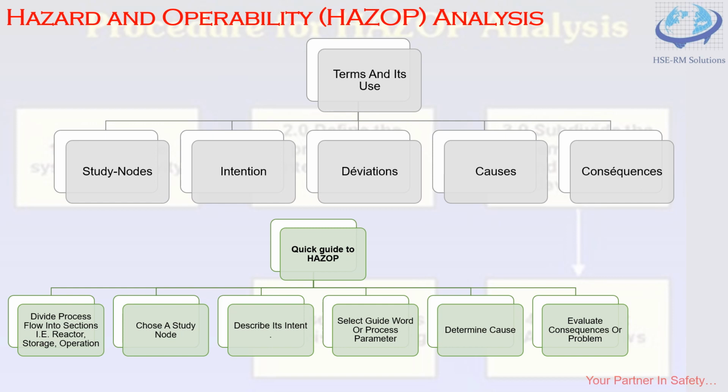These are reasons why a deviation might occur. Once a deviation has been shown to have a credible cause, it can be treated as a meaningful deviation. These causes can be equipment failure, can be a human error, or can be an unanticipated process state, that is a change in the composition, or an external disruption like loss of power. So these are the causes.